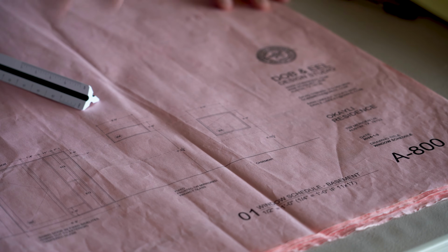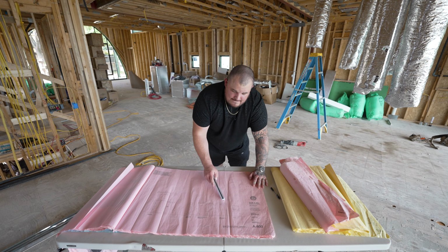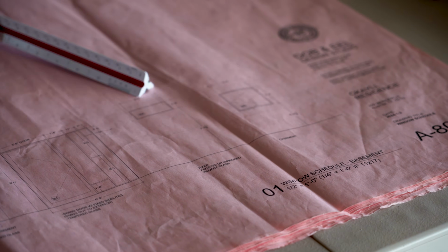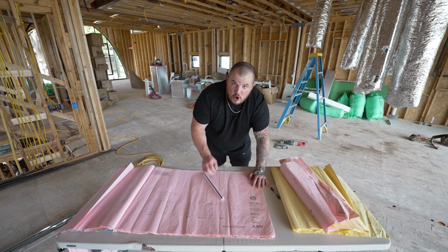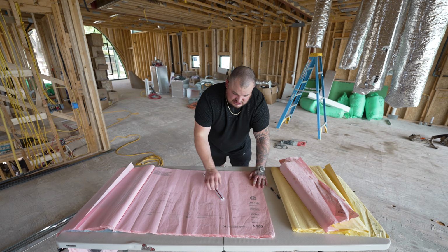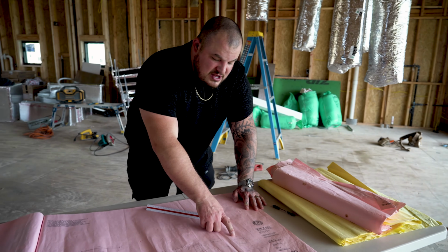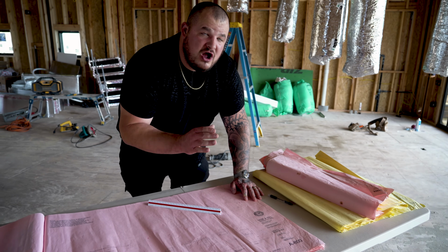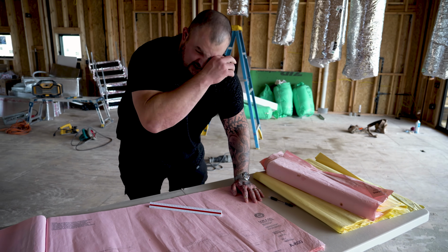But what I do for ease of access for the guys on site, I tell my window company that all the sizes that you see on the plan is what we're gonna make the rough openings to. So the window company can do all the homework of adding the 1/2 inches. But our framers know that this window is a 3 foot wide by 3 foot tall rough opening. It makes it so much easier.